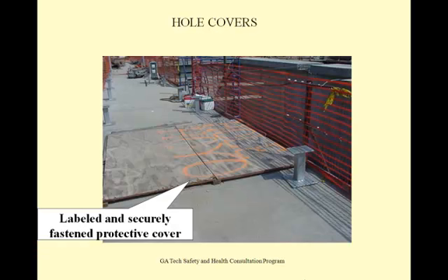If working around holes, which is a gap of 2 inches or more in size, the covering material should be securely fixed in place and labeled with the word hole. The covering must support the weight of 2 people and/or twice the weight of the heaviest vehicle that might drive over it.